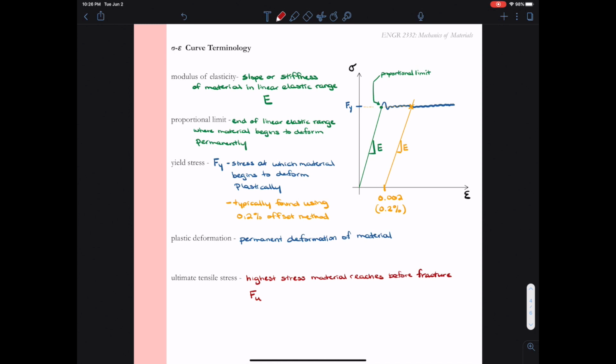Hopefully you came up with some creative ideas as to when yielding might be an acceptable design condition. There's many plausible scenarios out there. I'm sure you can look on the internet and find some other things particular to your area of interest for engineering. For me, I'm in structures, and so one point when we definitely allow for yielding to happen is when we design structures for extreme conditions like blast or earthquakes. When we do that, we design to allow yielding to happen in our members.